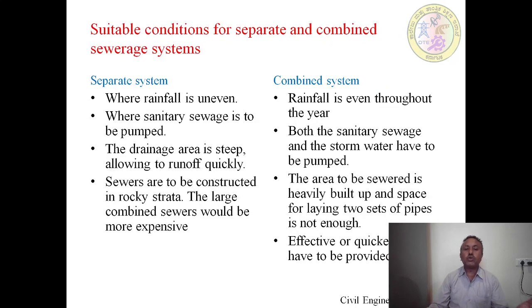Now the suitable conditions for separate and combined sewerage systems, which show the suitability of the two systems. The separate system we can adopt where rainfall is uneven and we cannot predict it, and where sanitary sewage is to be pumped. In that way, we can provide this system.